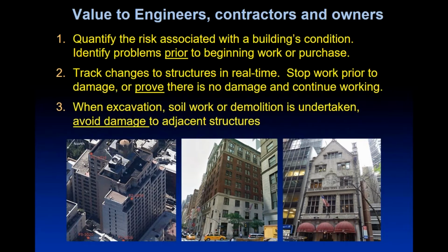For those of you who are geotechnical engineers, you will look at the characteristics of the soil, integrate all your information, and calculate a spring constant for the structure. You may distribute it. We can't do that, but we'll take an average value underneath the structure itself. So in that case, what we've got is a look at that soil spring constant averaged underneath the structure.